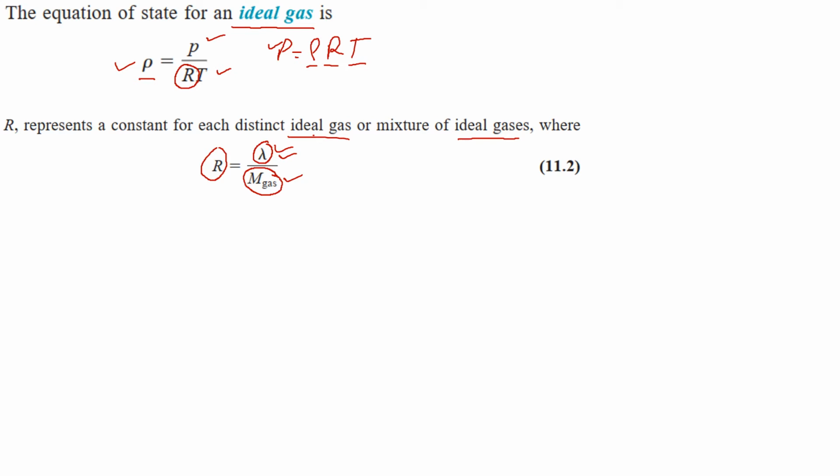Here we have covered the pressure and temperature. The next property, the important one, is the internal energy, and internal energy is defined with the help of specific heat capacity at constant volume, which accounts for the change in internal energy with the change in temperature. How does this equation come out to be like this? For that we will have to see the equation from the first law of thermodynamics, that any change in internal energy will be equal to the change in the heat content of the system plus the work that is done by the system or on the system.